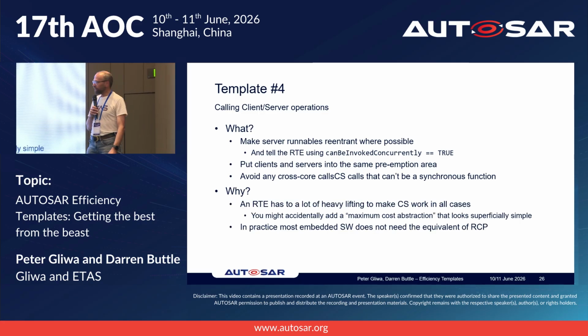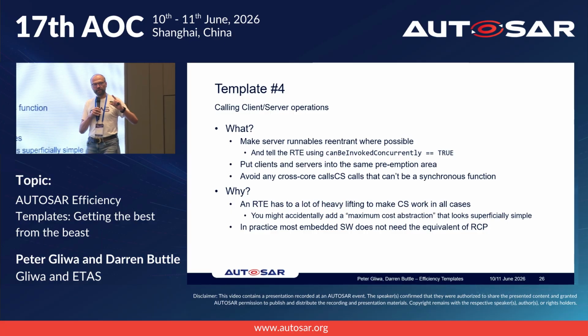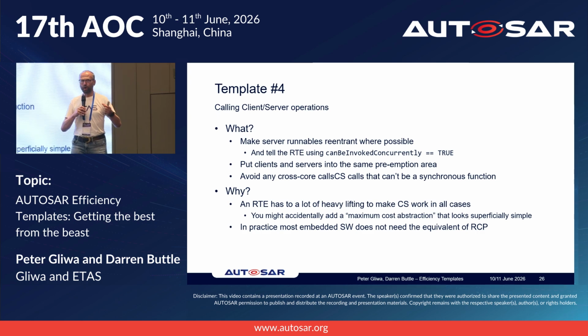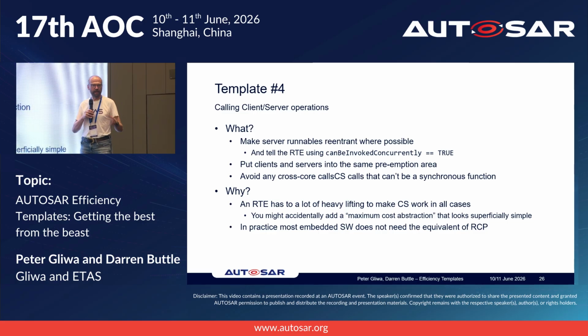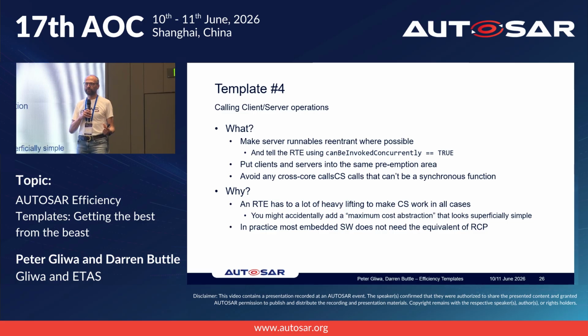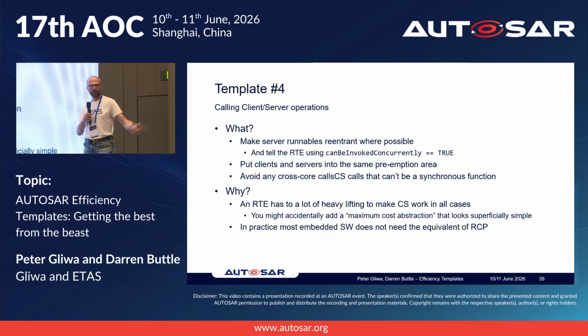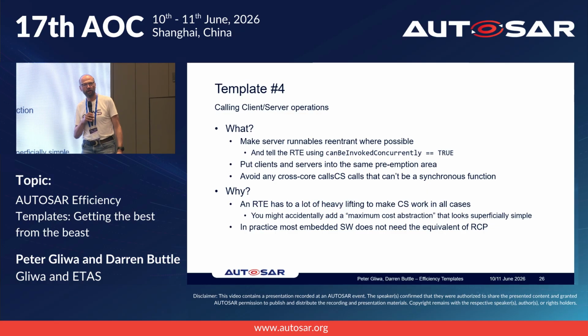And again, the reason for doing this is there's a lot of things in AutoSAR that are what are called zero-cost abstractions, things where you can have a nice, clean design model at the application code level, and we can make it possible with next to zero flash and execution time. But there are other abstractions in AutoSAR that, even if you implement them as efficiently as possible, they can never be cheap. So cross-CPU-core client-server can never be cheap. It's about 200 to 300 times more expensive than just a function call.